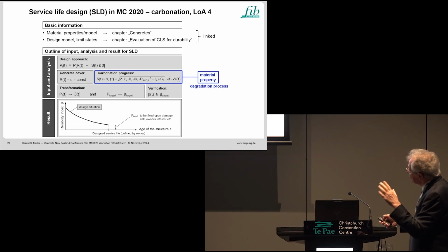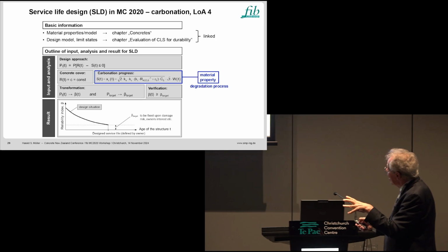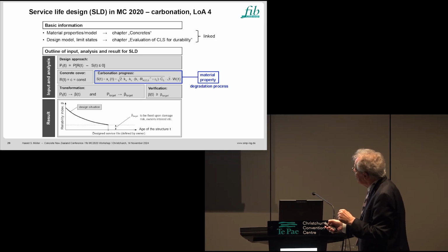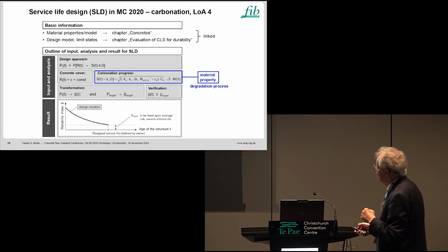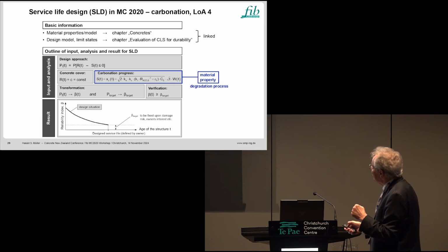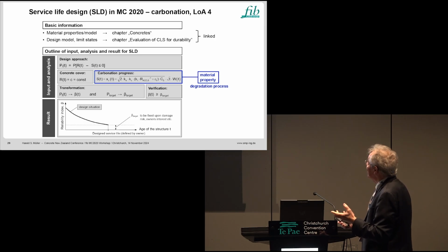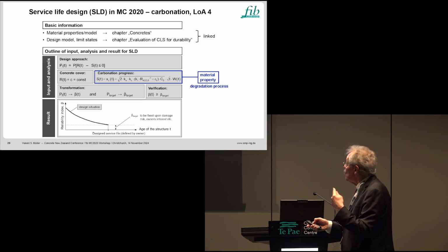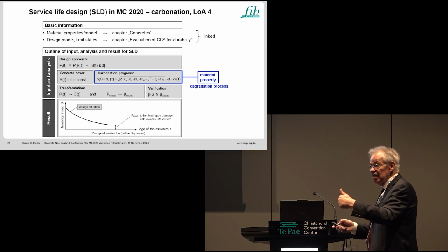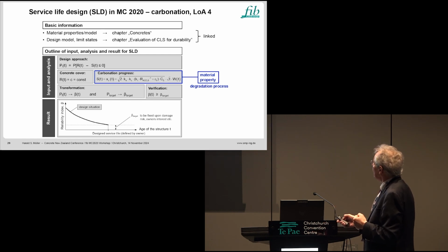Well, this summarizes the design, the input, the analysis, and the result of a service life design. This is the input, this is the analysis, and this is the result, the decreasing reliability with time. And the input is the material property, the carbonation process. And in this way, you can calculate the service life, which you would like to have for a desired service lifetime, or depending on your particular concrete.